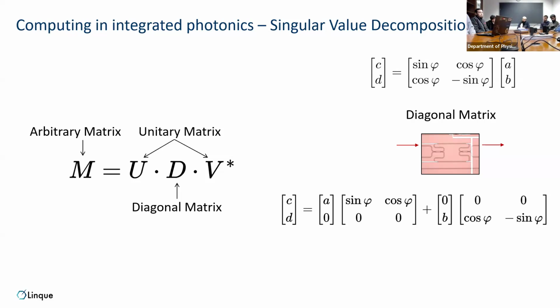If you look at the literature, a lot of people have worked on this. You typically see people reporting one measure and saying it's really good and ignoring the other, or the other way around. In principle, if you ignore all this encoding or do it really slowly and energy efficiently, then you have femtojoules per bit, which is orders of magnitude better than an electronic system. But if on top of that you want 100 gigahertz encoding speed, then you need really energy-intensive encoders. This can work in favor, but it's not a slam dunk.